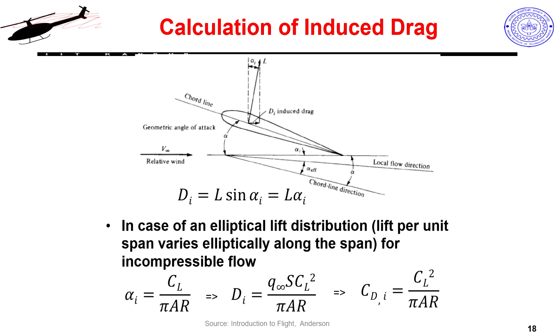So, what we are saying is that the induced drag is coming because of the tilting back of my lift vector, and the tilting back is happening by this angle, where alpha_i is my induced angle of attack due to the tip vortex. So, with that I can approximate my drag as L alpha_i, because sin alpha_i and alpha_i will be the same, the angle is going to be very small, maybe 1 degree, half degree, 2 degrees like that. So, for small angles we can easily apply the small angle assumption.